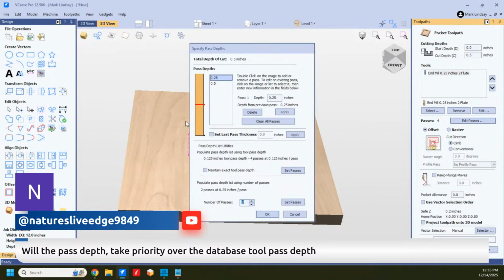The problem is we're going to have tool deflection to worry about. When a tool is taking off a lot of material and ejecting those chips, be it upcut, downcut, whatever, you're putting a lot of sideways stress on that bit to the point to where it can deflect just a little bit.